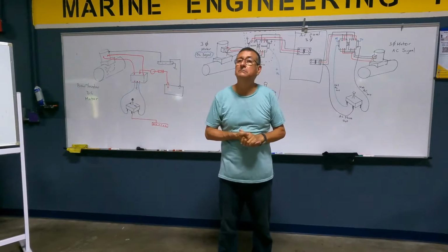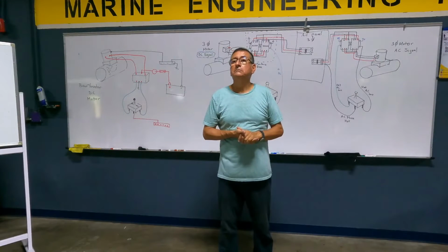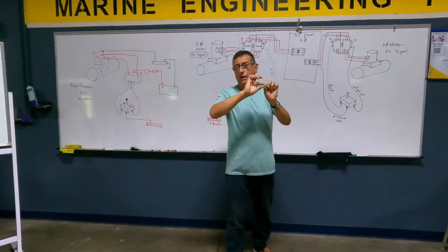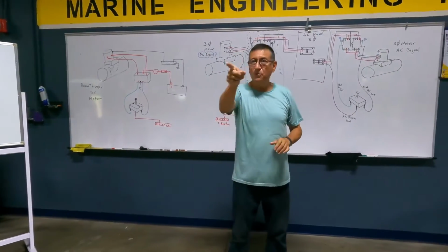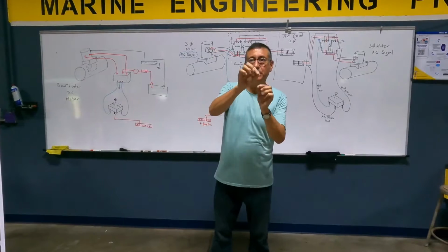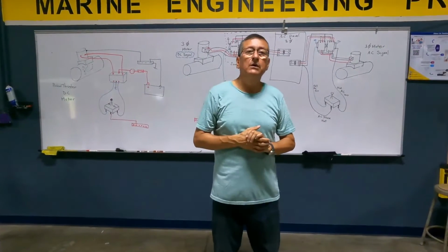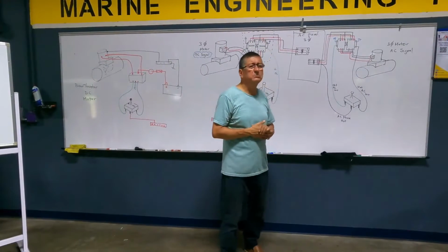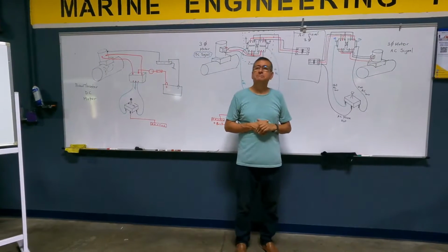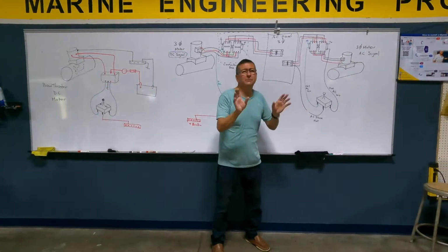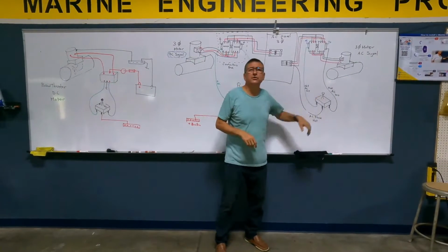When you wire those in, do you normally just split off a small wire off of one of the phases? Yes. From one of those phases, I connect the small wire, like the small wire that we had yesterday in the red one, you remember? Is there no need for a fuse on that? It's on its own breaker, a separate breaker. It's nice, no? I can install here a fuse, 5 amps or something like this, to protect the joystick.